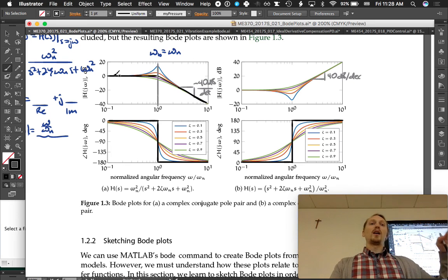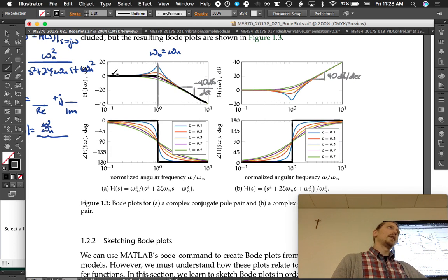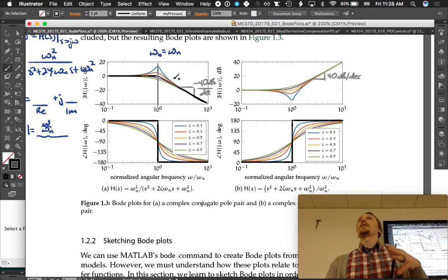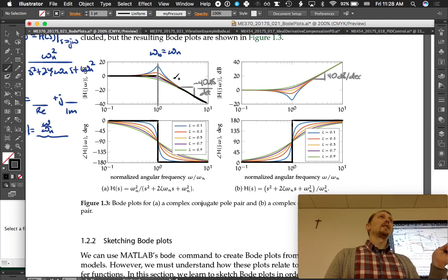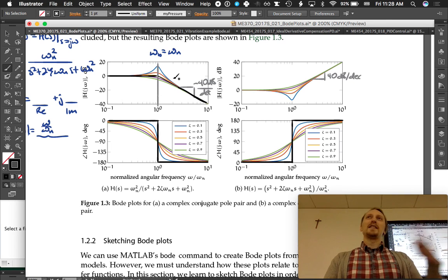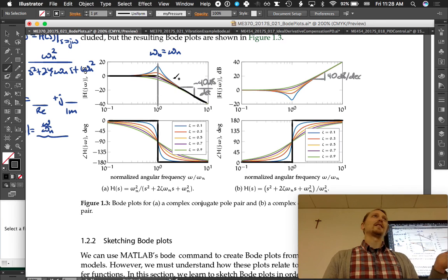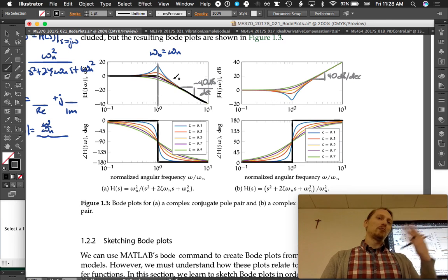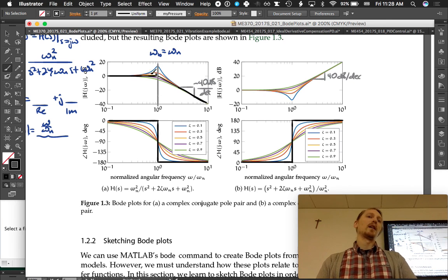If we operate at really low frequency, the force would just be the same. So very slowly, it's just going to be the same. And the motor, of course, is going to have to speed up, so it's going to go through this resonance to get there. But as long as it does so relatively quickly, it's probably not a big deal. If it hangs out there, that's when the problem starts. So I want to operate at higher RPMs than where our resonance shows up.